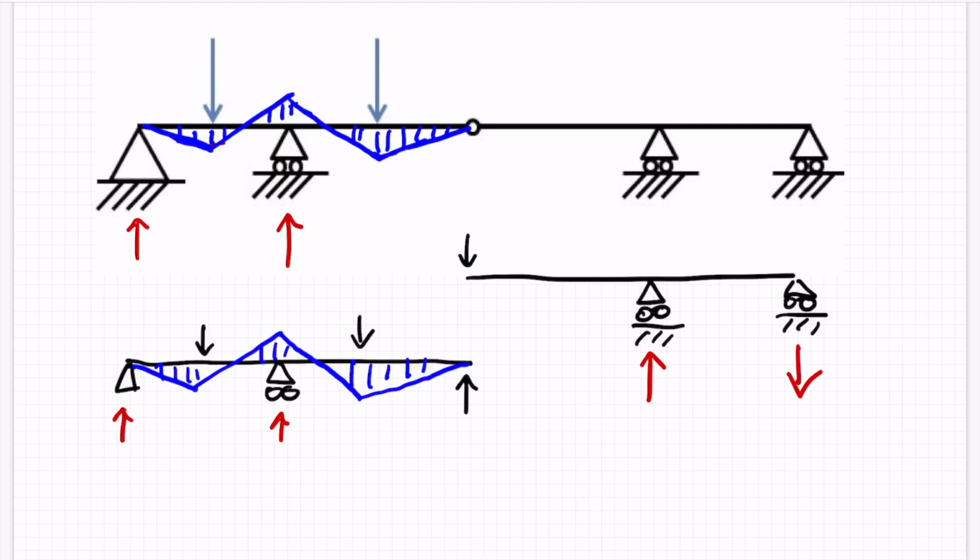Okay, and then let's fill in the rest of the bending moment diagram. As we go along here and look to the right, we're expecting this to, because that's going to try and pull the beam down, cause tension on the top side there. And it's a linear variation. Then as we go further along the beam, right to left and only considering the right, we've got this opposite force, so we expect a reduction of the bending moment.